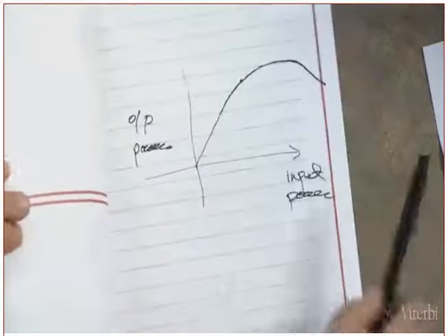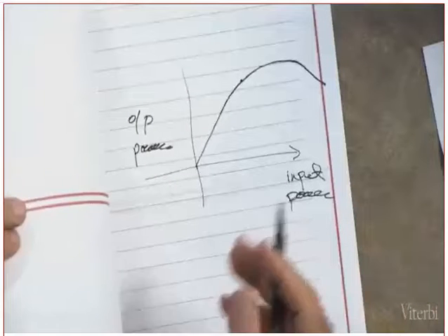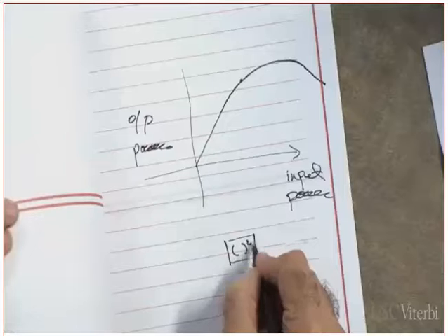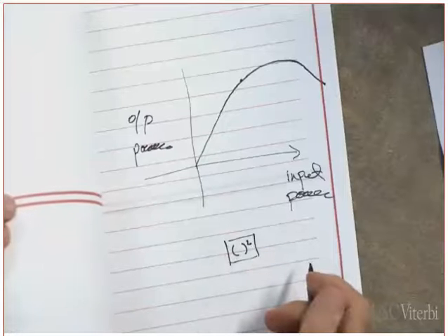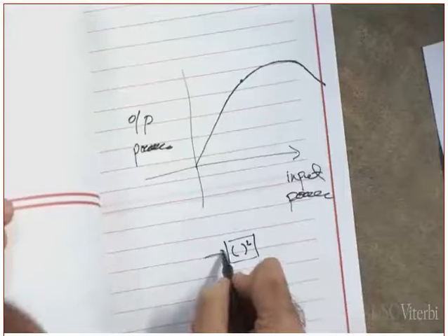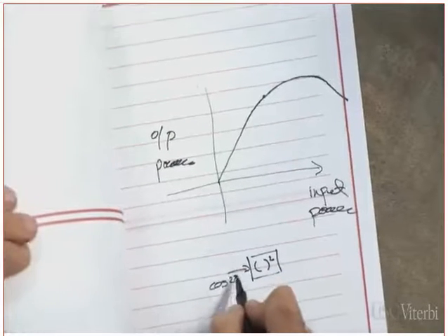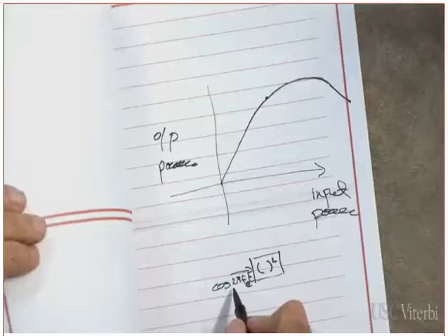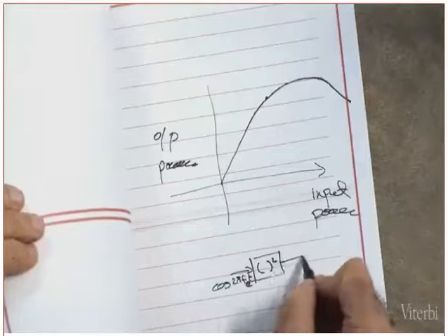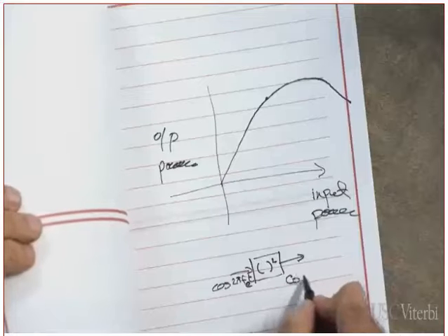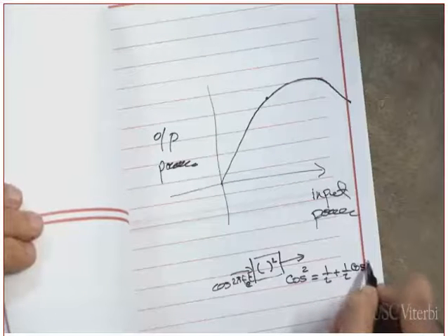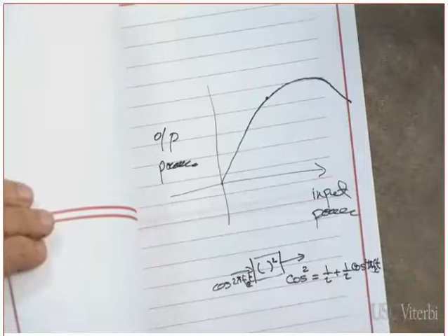Clear? I want to show you a very simple, silly example, just to show you the point. Let's assume I have a square law device. Question: is this a linear or non-linear system? Non-linear system. Apply cosine 2 pi f naught t, or f c t, doesn't matter. How many frequency components do we have here? I have cosine squared, which is equal to 1/2 plus 1/2 cosine 4 pi f c t. Did we create the second harmonic?